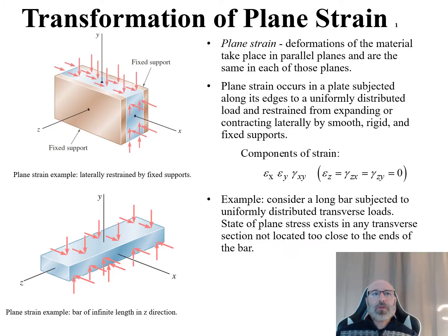So we'll get started with the topic of transformation of plane strain. So what is plane strain? Plane strains are the deformations of the material that take place in parallel planes and are the same in each of those planes. Plane strain occurs in a plate subjected along its edges to a uniformly distributed load and is restrained from expanding or contracting laterally by smooth, rigid, and